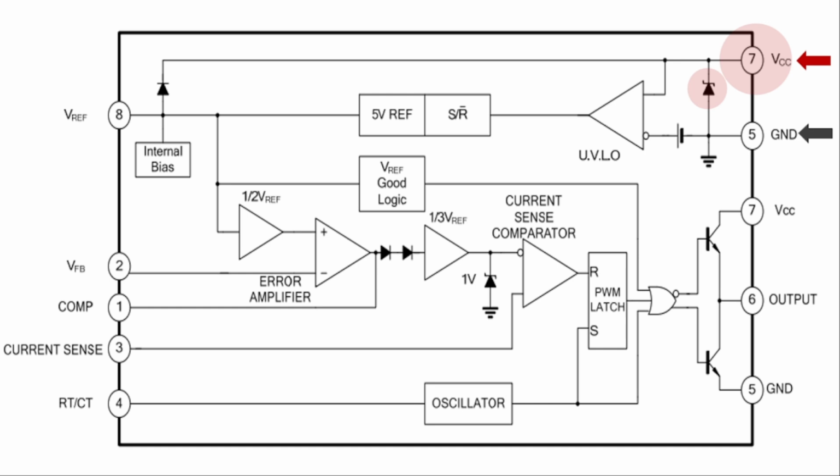working. After that, you will see that the next comparator is the undervoltage lockout. This means that if you give the input voltage below a limit, then in this condition, your IC will go into the undervoltage lockout mode, and this undervoltage lockout provides protection to the MOSFET. That is, your IC can operate, but the MOSFET will not get the output. It needs to switch on and off.